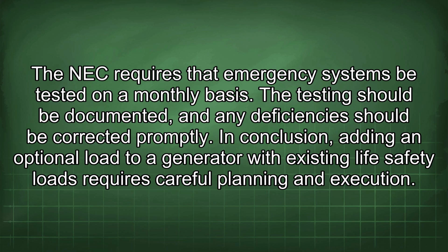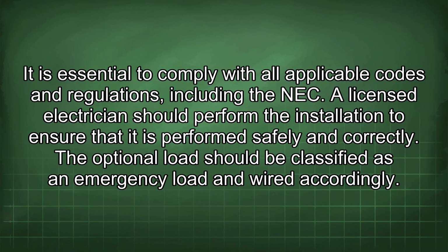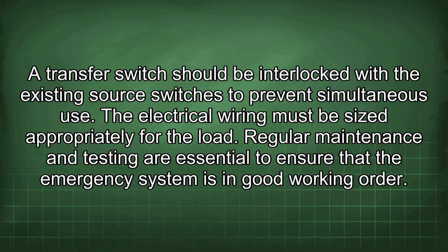In conclusion, adding an optional load to a generator with existing life safety loads requires careful planning and execution. It is essential to comply with all applicable codes and regulations, including the NEC. A licensed electrician should perform the installation to ensure that it is performed safely and correctly. The optional load should be classified as an emergency load and wired accordingly. A transfer switch should be interlocked with the existing source switches to prevent simultaneous use.